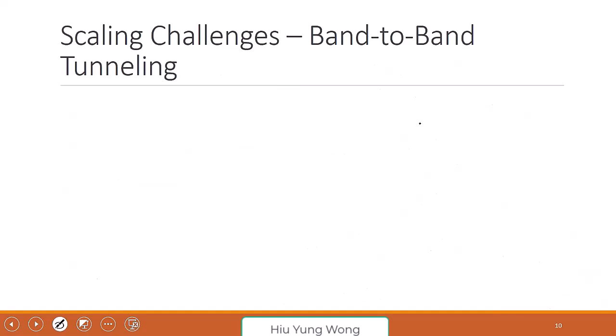Okay. So let me go ahead, right? Now then, okay, I introduced this subthreshold slope. Now I want to discuss something. Now, when you scale, we keep saying that we want to increase the substrate doping, right? What's the problem of increasing? What's the goal? Why we want to increase substrate doping? Do you remember? We just discussed why we want to increase the substrate doping. Is it smaller depletion width? Well, you reduce the smaller depletion width. Looks great, right?